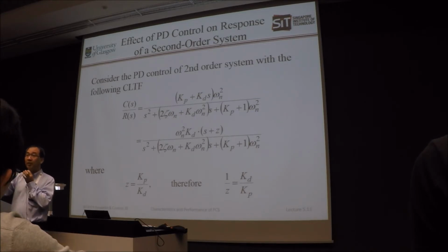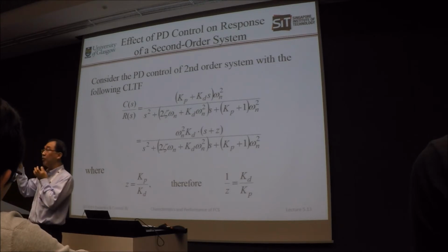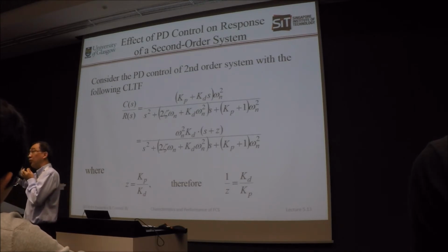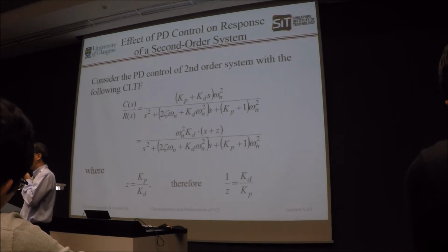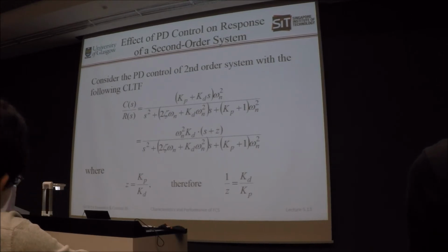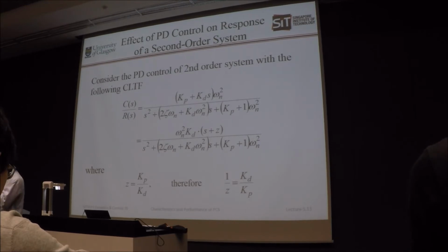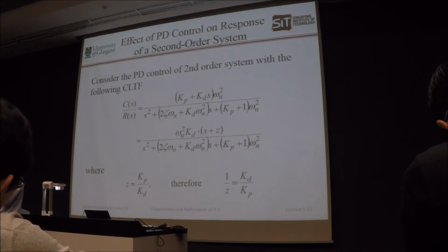We do mention that the whole idea of the closed loop transfer function is to tweak your pole location. When you design your feedback controller, you are designing it to tweak the closed loop pole location to a location that you are comfortable with. You want the system to have that kind of behavior.